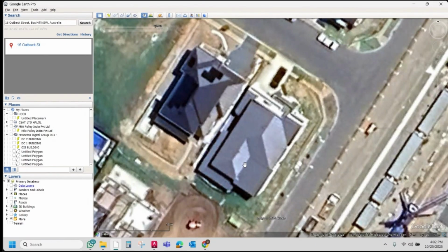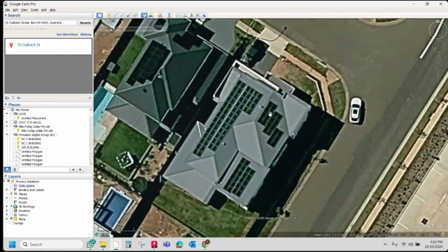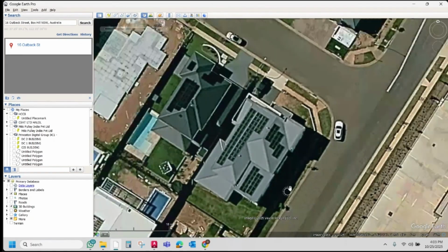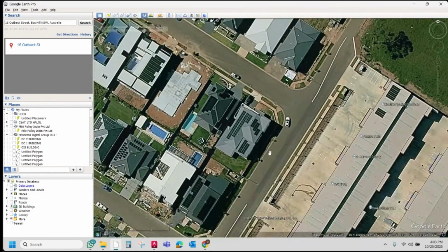One is a normal slope, this is a huge slope, and this is the roof. Then I just place the modules over here in straight lines, then here straight lines. But what they actually did here is only three lines, and here they have covered and occupied the maximum area. So this will be more helpful to us while designing.